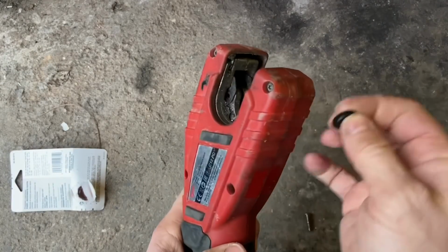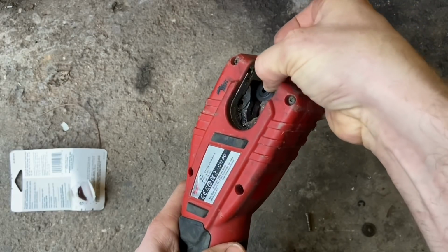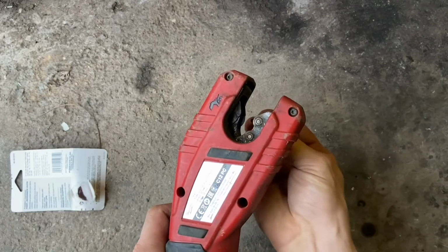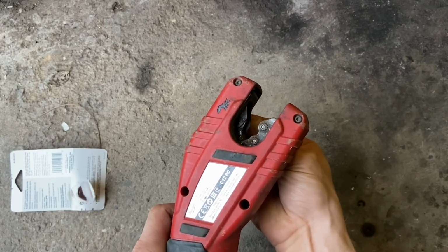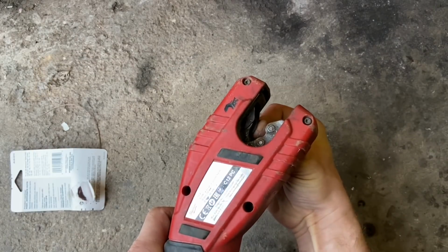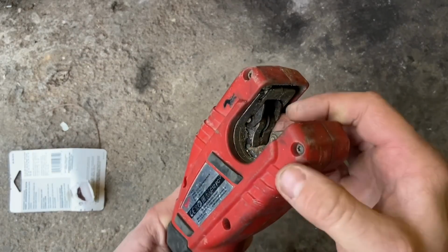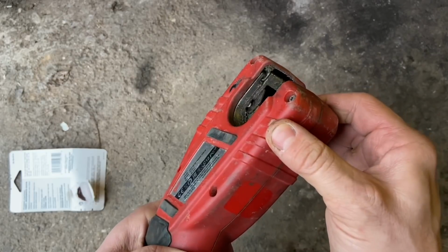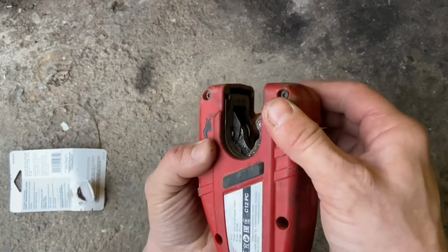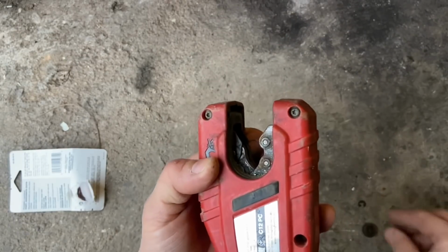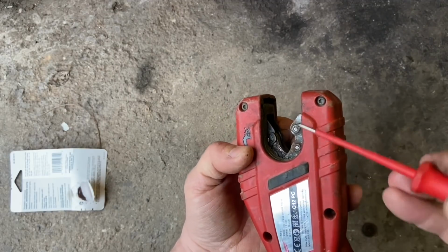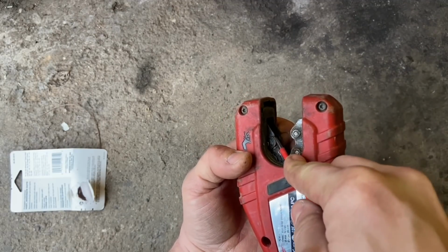And then the new one, pop it back in there like that, and just push the pin back up through the middle of it. You might have to just wiggle it around a little bit. See there, I've got my new cutting wheel in there, and then I've just pushed that pin up. So what I need to do now is, while I'm holding the pin up, pop my little clip back on and just push it on.